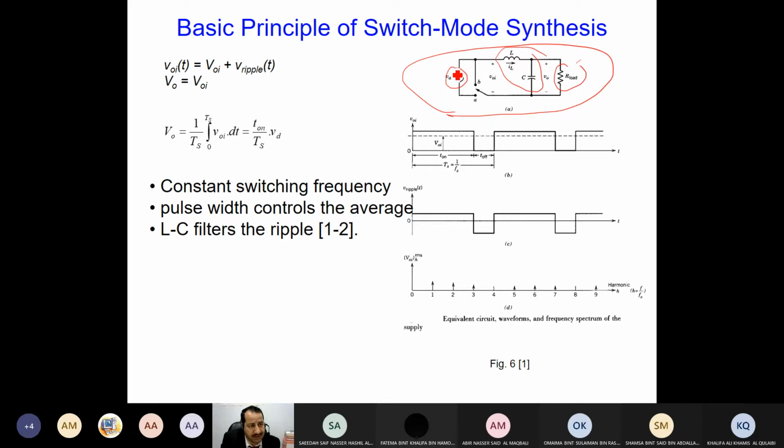Now here we have a DC supply. In the previous slide, the transistor, diode, and the transformer with the 3 windings work this way, like a switch. Either it is on A, so the circuit is closed and the current will flow here, and we have a closed circuit. Or it will be on B, the supply will no longer be available, and we have only the inductance in parallel with the capacitor and the load.